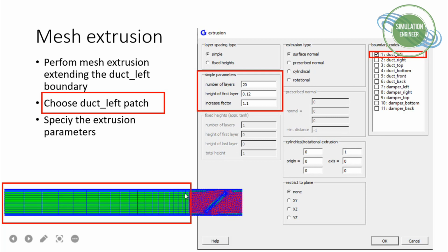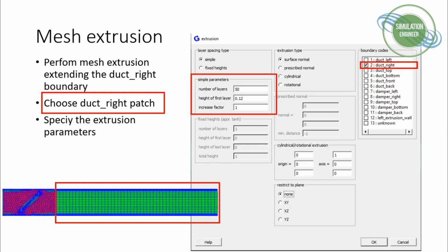And it's really quite a cool feature in case of complex geometries. If you don't want to fill your complete fluid domain with triangular elements, you can just locally mesh it with a combination of hybrid elements, like tetrahedrals and prism layers, and the rest of the domain with the help of the extrusion feature. So you can extend your domains, and one will also get very good convergence. Okay, so these are the steps which I will be using to generate our mesh. So now let's move to the real part. Let's move to NGrid and apply all these steps.